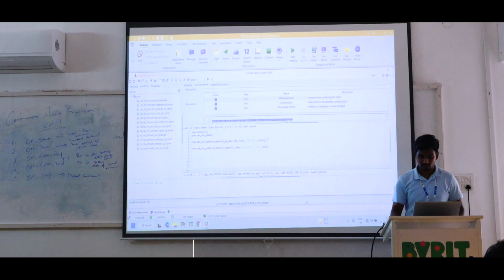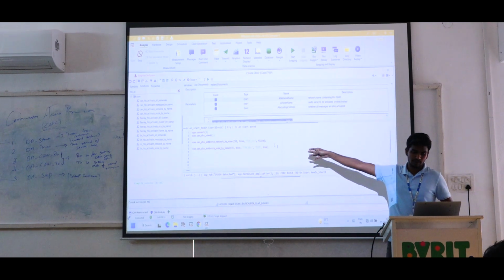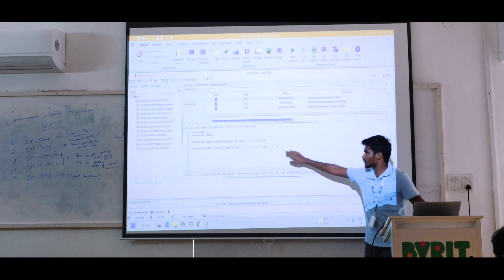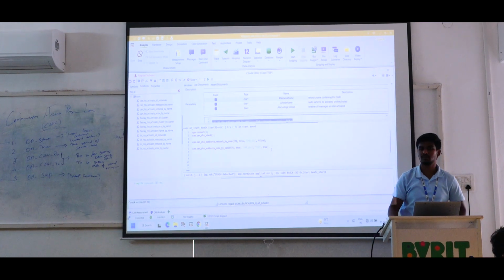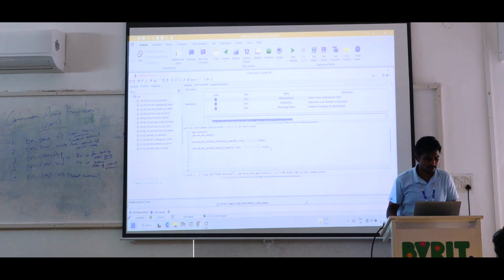Signal: next, there is no need for a signal, because here we can put the advanced option as both true for this line also, which means the first is for turning on the node and then the network. The last true is for activating the message, because the TCU has only one message, so we don't need to give the message name. Suppose we need special scripting for that, we have one more option, activate message by name.